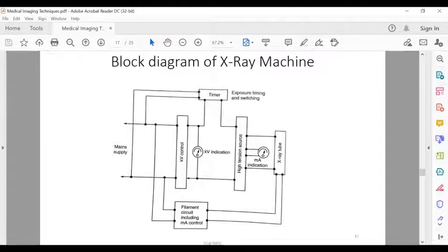So this stop bath stops the development action, and this stop bath is acid type as per the recommendation of the film manufacturer. Normally, the emulsion is properly fixed after immersion into the fixing solution for twice the time it takes for clear appearance. And the normal light in the dark room is switched on after disappearance of the hazy emulsion.